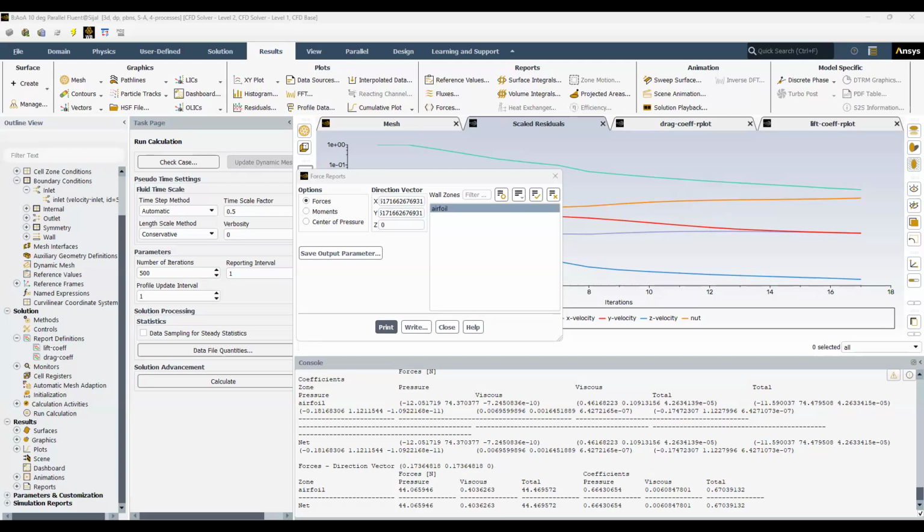And in the traditional way of aerodynamics, they are applied at 30% of the chord. So you can show the same angle, but in this case you will show the drag and lift in this way, okay, from 30% of the chord length. Okay, so now what about the lift and drag coefficient? The drag coefficient will now be converted into two components.